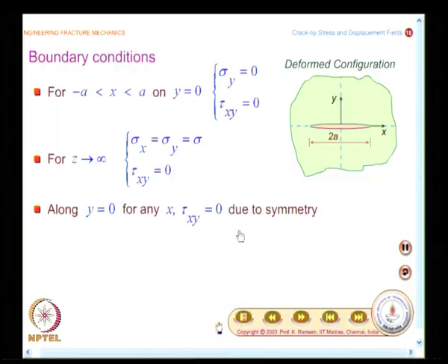So, that means along the crack axis there is variation of maximum shear stress, and here you are making a statement along the crack axis in plane shear stress is 0. This is correct, but what we would show later is by imposing tau xy equal to 0 without our knowledge, we have also imposed maximum shear stress is 0 in the process of the solution development. This was not looked at by people in the initial stages.